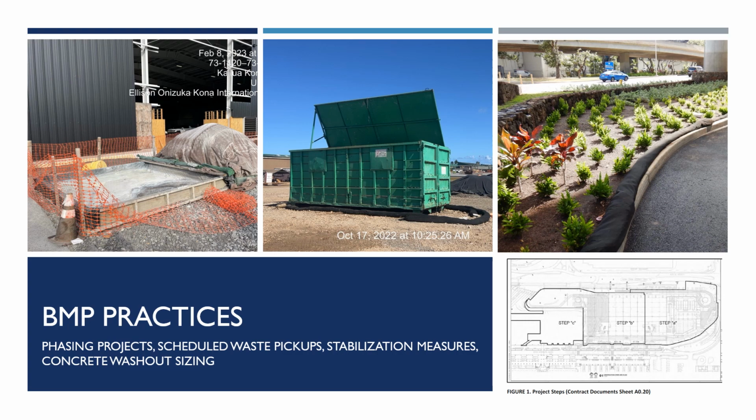BMPs extend beyond physical applications on site. Proper planning both prior and during construction can aid project teams to effectively manage BMPs associated with site activities. Phasing projects could decrease the effort spent maintaining BMPs over the life of the project. Scheduling waste pickup sooner could decrease effort spent maintaining covers for waste stockpiles stored on site.